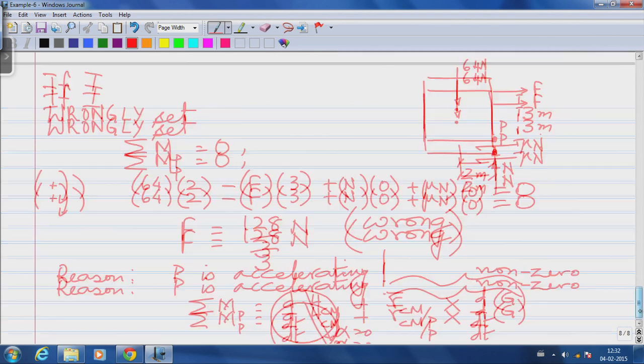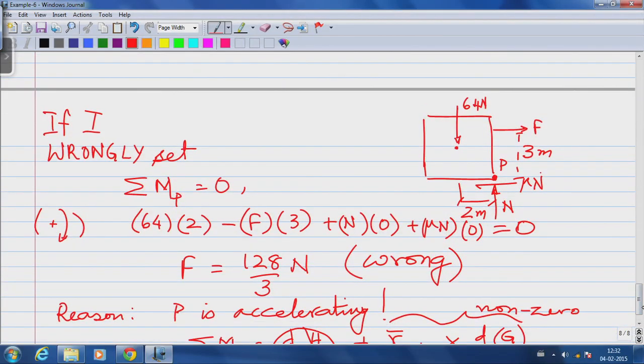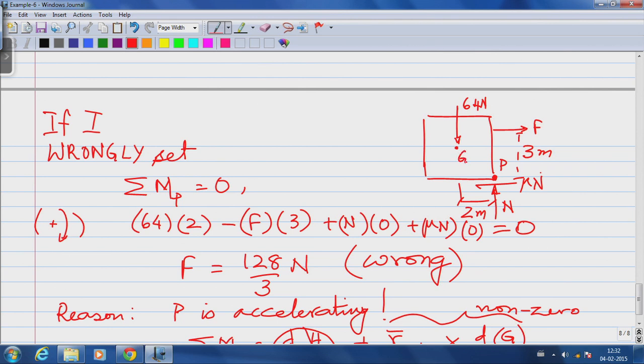So, you have to be very, very careful that in dynamical calculations, when you are calculating the dynamics of bodies, please be aware to only take moments about the center of mass. If you blindly did this for all the problems, you would never run into problems. You do it carefully, make sure you keep track of all the signs, you would always get the right answer. The math would be slightly more complicated. Like in this case, I have to account for the moment due to the normal reaction.